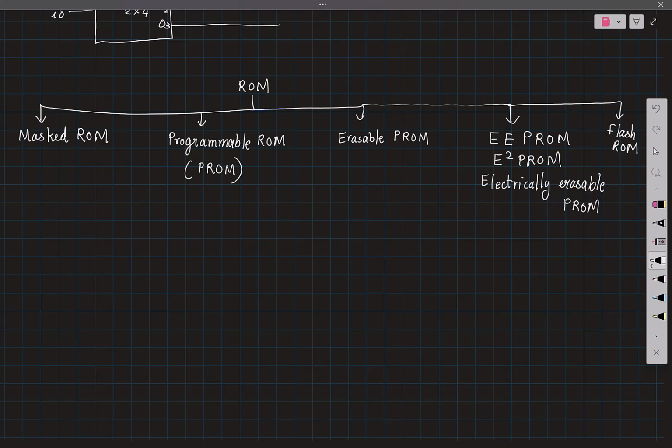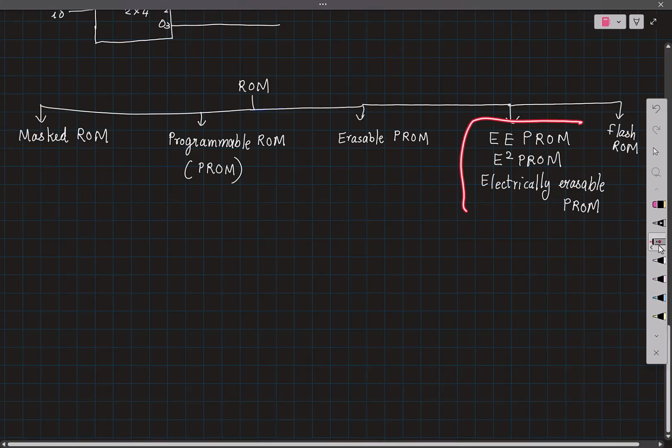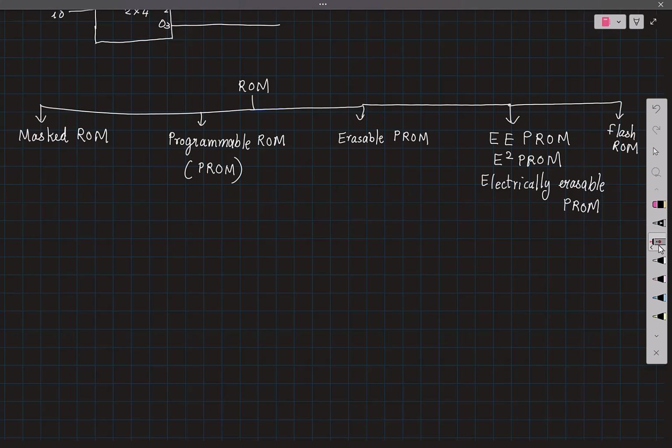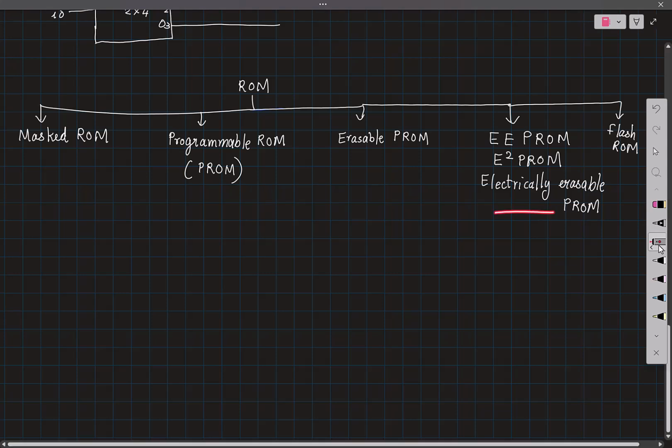Okay, so there are different types of PROMs, and typically you are likely to work with, this might be of the most interest to you, because the equipment needed to read and write into it, reading is very easy, of course. The equipment needed to erase the content and write into it is going to be much simpler if you use an EEPROM or a flash PROM.